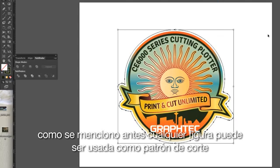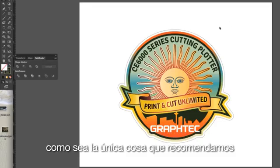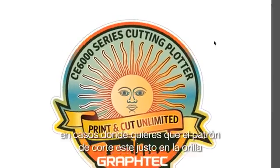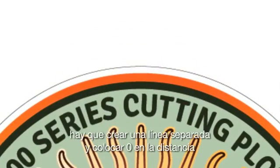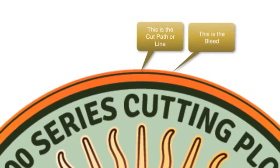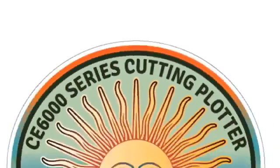As mentioned before, any shape can be used as the cut path. However, the only thing we suggest against is using part of the design as your cut path. This can create difficulties. In cases where you want the cut path to be right on the edge, create a separate outline and enter 0 for the distance. In this case, you may want to bleed out the design beyond the cut line. This will remove any chance of a sliver of white space occurring.